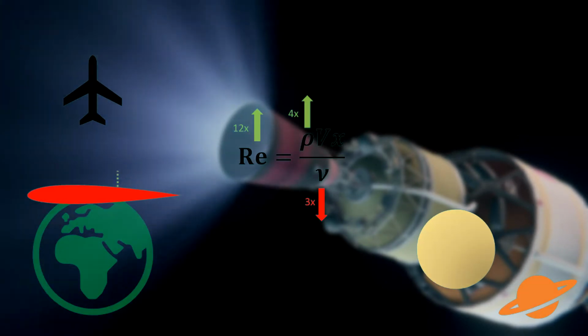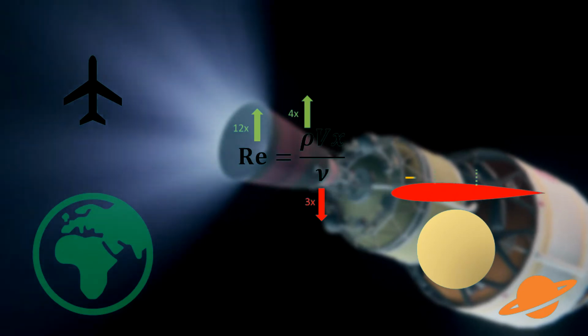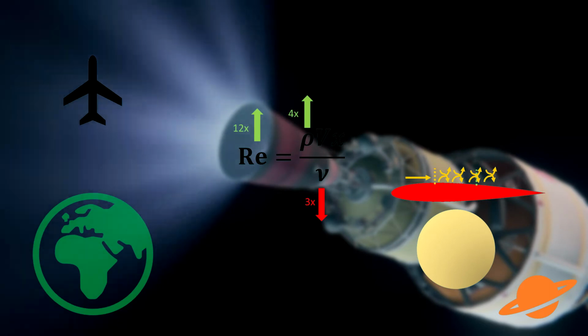Let's now consider the same wing section on Titan. The transition to turbulence occurs much earlier, and so the boundary layer drag is much greater than experienced on Earth. If you sum up this increased drag across the entire wing, the need to minimize wing area becomes clear. Fortunately, the lift equation we just explored permits this on Titan.